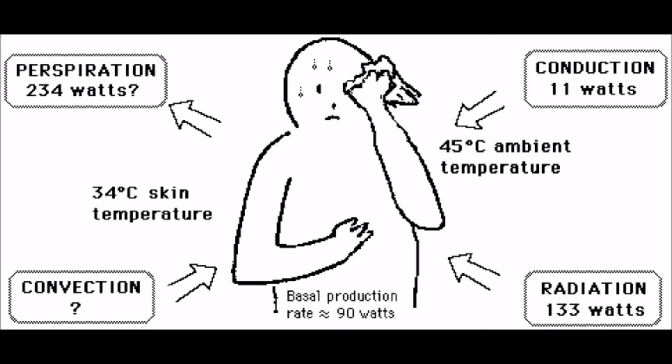Okay, that is for the convection part, and now we go to radiation. Radiation is when heat radiates across the space between you and the objects in your home. If objects are warmer than you are, heat will travel towards you. Removing heat through ventilation reduces the temperature of the ceiling, walls and furnishings, which means the cooler your surroundings, the more you will radiate heat to the objects rather than the other way around.